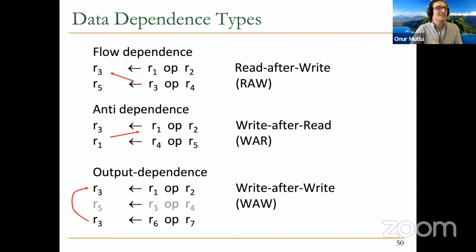If you always write the result at the end of the pipeline in sequential order, you don't have a problem with these anti-dependencies. Similarly, with output dependencies, you don't have that problem. If you look at the output dependence, an earlier instruction is writing to a register, and a later instruction is writing to the same register. Again, these have nothing to do with each other, right? There's no true data flow between the instructions. This exists because you don't have enough register names. This could have been register 1000 or register 55 if that was available, right? It is not available. That's why this is register 3.